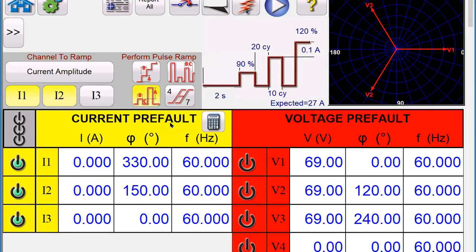I will show you the A to B. So we're actually showing 2 currents here, A to B, 180 degrees out, and we're also doing the same parameters, right? Because the 50 element is the same whether I do 3-phase, single phase, or phase to phase values. And then now we need to know the expected value. This expected value is the setting that I pulled from the settings that you saw earlier. So now we're going to run this test.